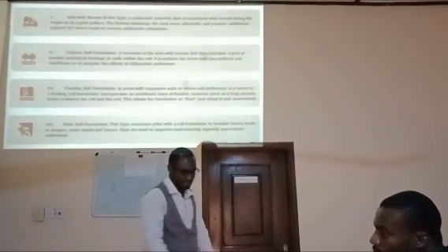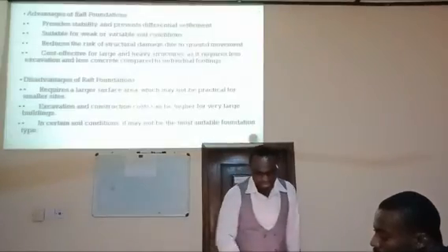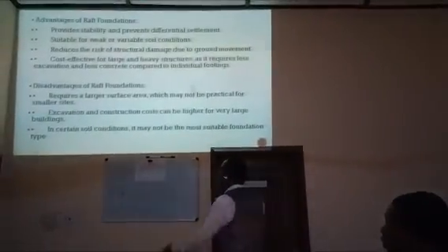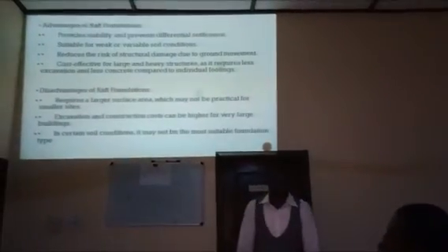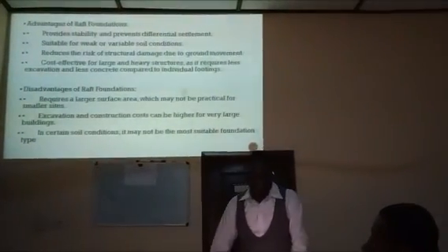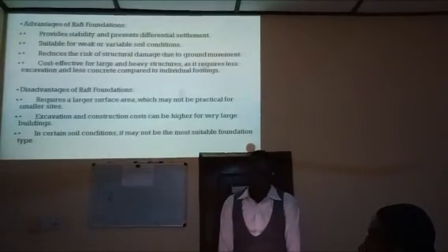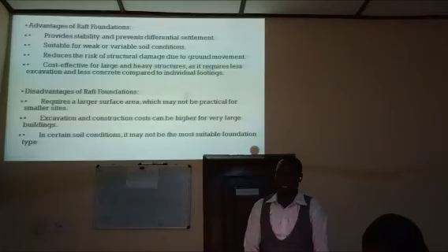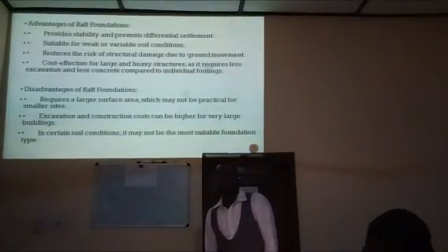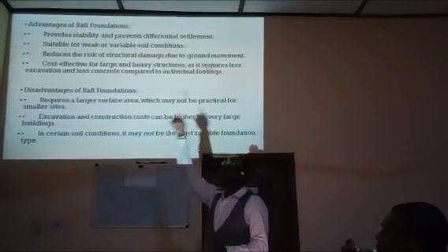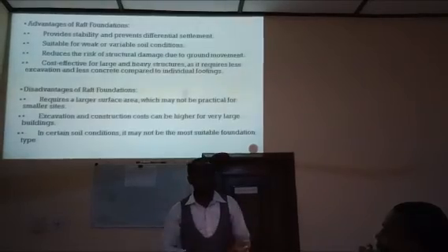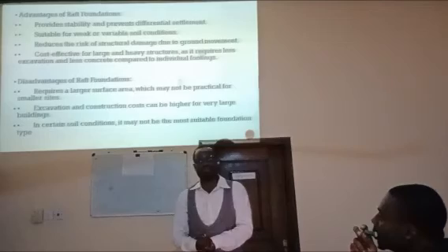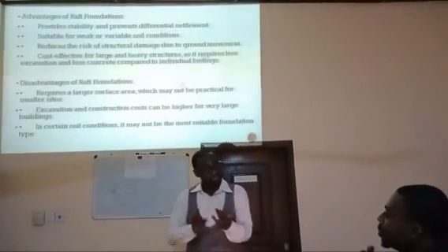And of course, it's more expensive. That's one of the disadvantages. Far more expensive because of the amount of concrete and reinforcement and so forth. Okay, then it reduces the risk of structural damage due to ground movement. Then it is cost effective for larger and heavy structures. Yes, they are comparing it with structures that would need deep foundation. Deep foundations are very, very expensive, generally speaking. But compared with deep foundation, raft foundation is cheaper.